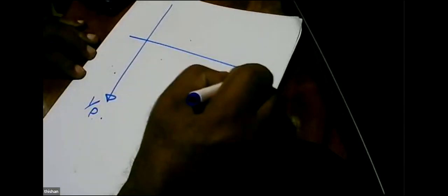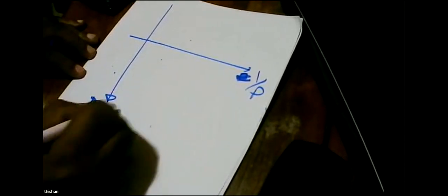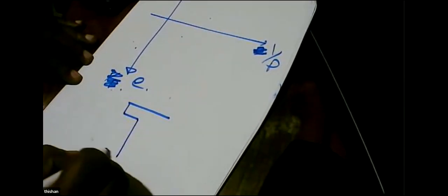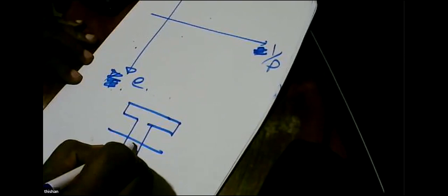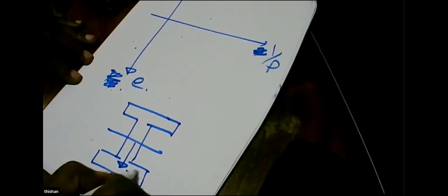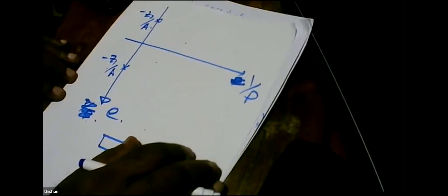So this is one of the, and this is C. We have the eccentricity measured downwards, and you know the reason, because if you take a section, we measure the eccentricity downwards, E downwards. So this diagram also is drawn downwards, and this is at 1 OA, this is at 2 OA. Again, you can see Z1 is negative, minus is positive, so this is a positive quantity.